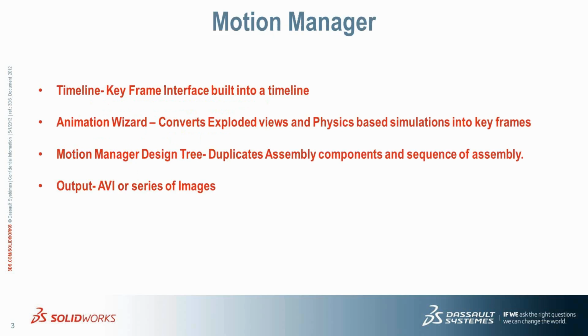The Motion Manager is kind of like the add-in. Now, for those of you who have been around SolidWorks for a while, there used to be a SolidWorks Animator product, and that has embedded itself in recent releases directly inside of SolidWorks so that you don't have to turn on this Animator tool. What we do have to turn on, however, is the Motion Manager. So I'm going to show you how to do that.